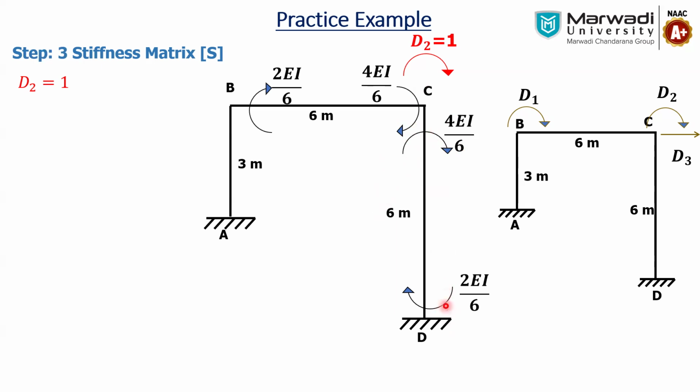We will not consider it for BC. There is some reaction, but there is no use of those reactions as of now in this stiffness matrix. Here, both moments are clockwise, so the reaction will be from the anti-clockwise couple. Here it is on the right hand side, and here it will be a left hand side reaction, which is nothing but 6 by L square.